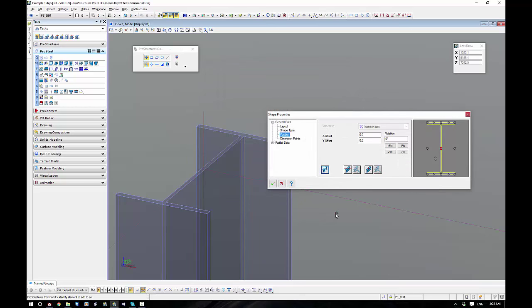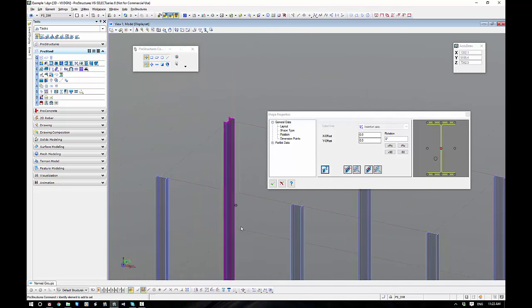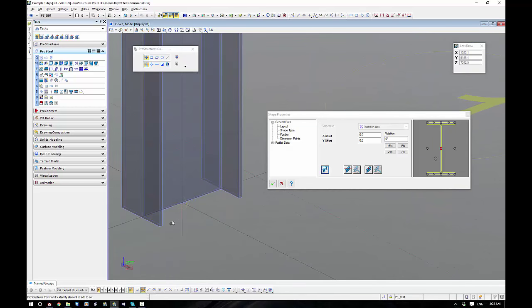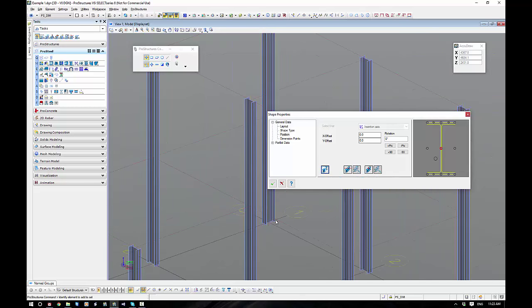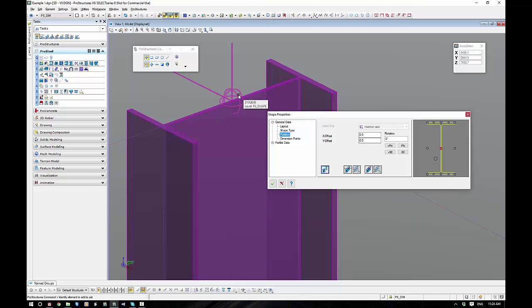All right, in here in particular is the rotation and layout of the object. At the moment, my ECS 0 datum should have been down the bottom because we went bottom to top, right? Okay, if I did something wrong and I wanted to flip it up the other end, here is the flip switch. You can just flip it up the other end so that the 0 is now up the other end. Here it is up here. See?